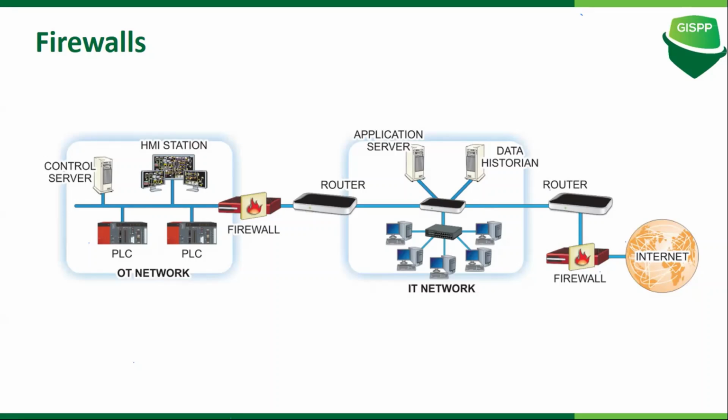So what I will do is take out that data historian server. I will either put it in the IT network, which is also risky, or I will create a DMZ. So anyone who needs to access the data historian server should not go inside the ICS network and can access that data from the outside.